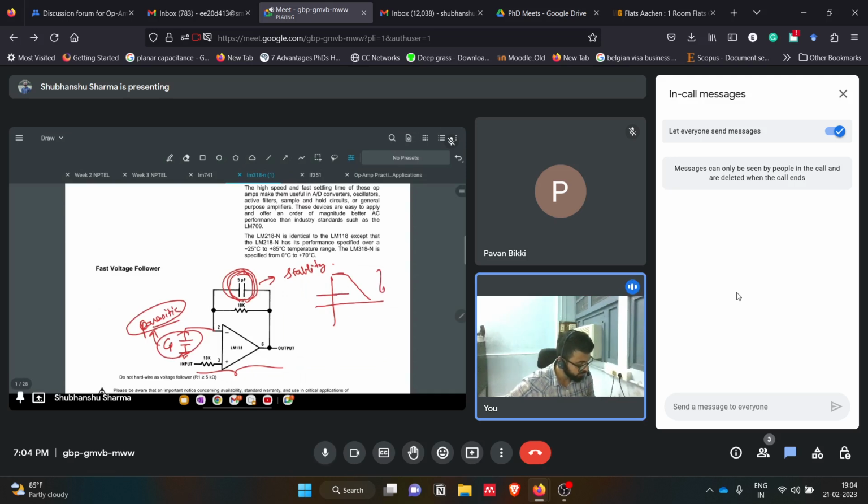This is frequency, and this is gain. Because of this parasitic capacitance, there is another characteristic. What happens when we look at the phase? This is basically the Bode plot: this is the frequency response and this is the phase response. The phase can tend toward minus 180 degrees, and they have this junction.